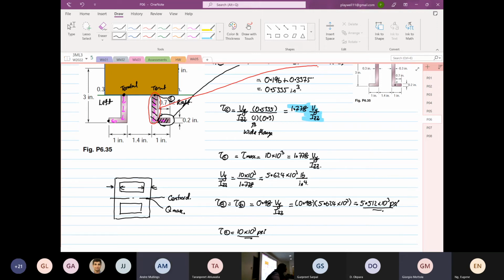No, I'm saying in the notes you said that tau max is at the centroid, but you never said to check it with your thickness as well. Okay, that makes sense. You have to check your thickness. You cannot say, oh, it's always at the centroid. You have to check your thickness. That's why in your question, I gave you a hint: check the centroid and check whether it's at another point. Yeah, deliberately.